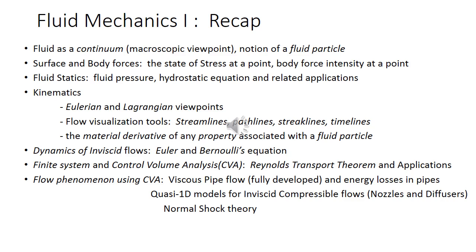Then after statics, we naturally moved on to kinematics, and there we learned about the Eulerian and Lagrangian frames of reference, or two viewpoints for describing the motion of fluids, because kinematics typically deals with describing the motion in terms of velocities and accelerations. So there are two fundamental viewpoints, the Lagrangian being the more natural one, where you focus on our smallest entity, which I have defined earlier, the fluid particle. If you focus on a fluid particle and track its motion, then you are essentially adopting the Lagrangian viewpoint. Whereas if you talk of all fluid particles in the fluid, actually they are infinite, but you can talk in terms of their spatial location. So at each point at a given time, there is always a fluid particle.